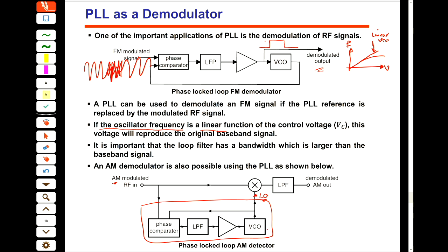So I use an oscillator, and then based on the carrier of the signal that I received, I try to lock these two and then down convert my signal. And this is actually the low pass filter too, because the signal that we received is LO plus RF and LO minus RF, and then we are interested only in this one. And theoretically, LO and RF would be opposed to each other as much as possible, right? Yes. Yep.